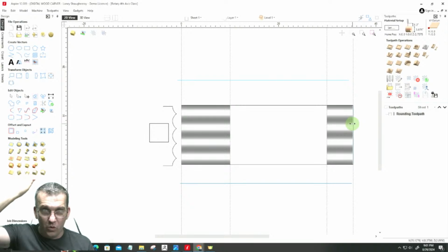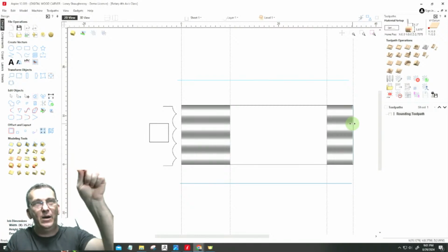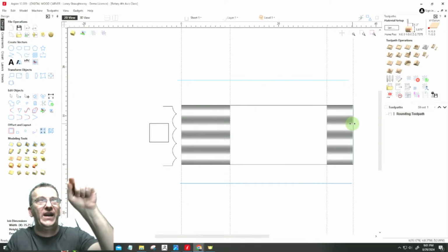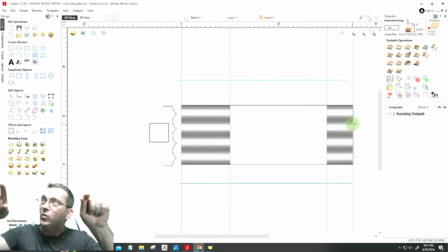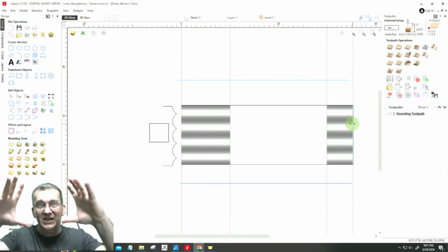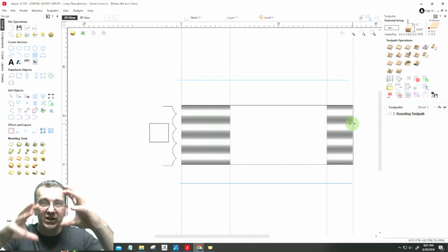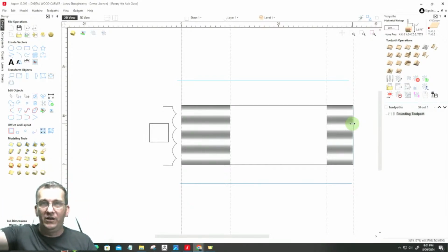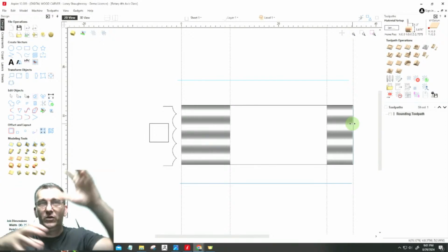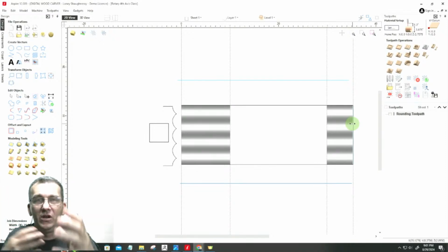It's designed for factory floor programming, where the operator is standing at the machine on this factory floor, punching in numbers, saying how big the bit is, what speed it needs to go, how fast it needs to turn, where it's got to start, where it's got to end. He's answering this little widget, if you will, to create this G code right there on the floor, instead of someone in the office drawing up a design in CAD CAM software and sending the model out to the operator. It's done right there on the floor, and it's called conversational machining.